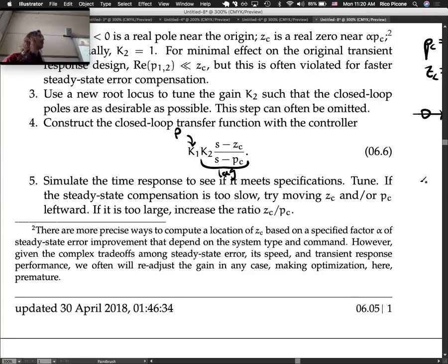So 10 degrees times maybe the controller gain of 5. And then maybe there's a differentiator, maybe there's an integrator in there. You estimate that with some numerical approximation of a derivative or an integral by, say, summing up errors over time for an integral and taking the difference over time for a derivative term. And then you multiply it all out till you get your voltage that you want to apply to the motor, and then you go through a digital to analog converter and amplify it and deliver it to the motor.